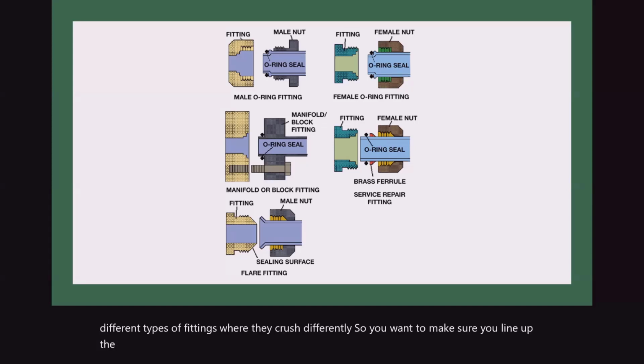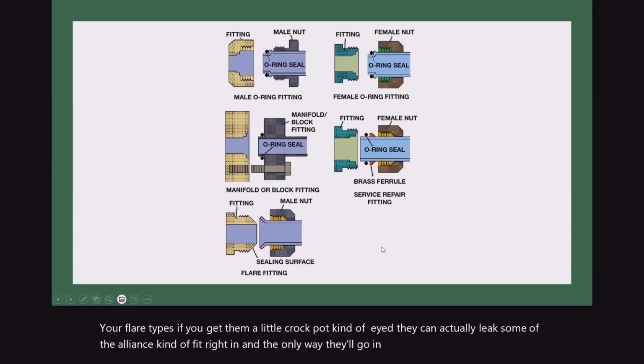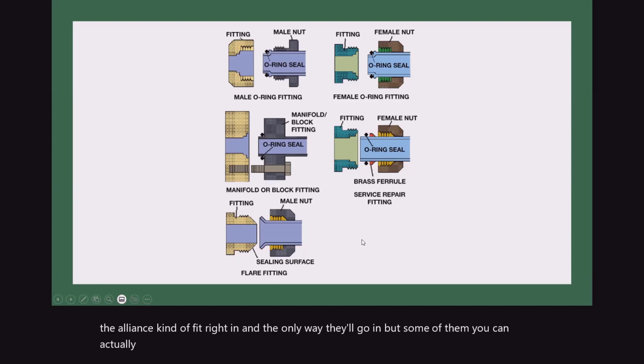I've seen some poor lineups and it caused them to leak, especially on your flare types. If you get them a little cockeyed, they can actually leak. Some of the lines fit right in, and that's the only way they'll go in, but some of them you can actually get off center just a little bit.